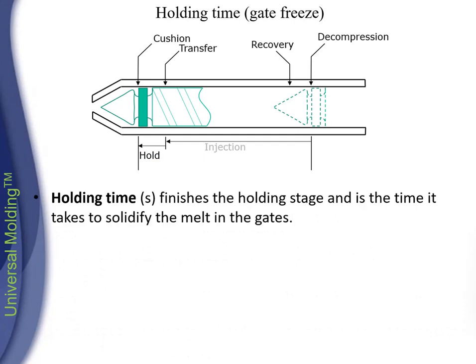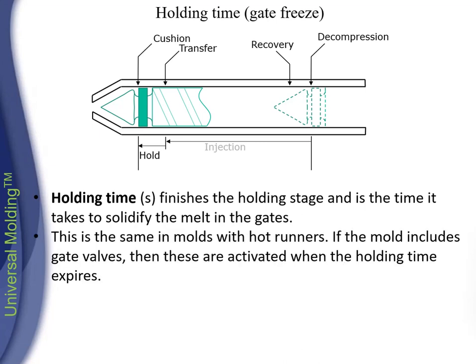Holding time. Holding time finishes the holding stage and is the time it takes to solidify the melt in the gates. This is the same in molds with hot runners. If the mold includes gate valves, then these are activated when the holding time expires.